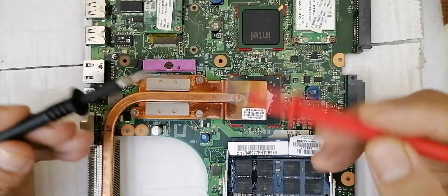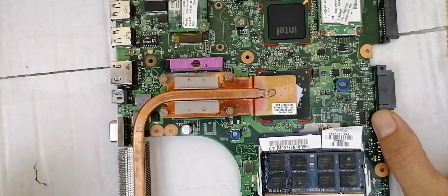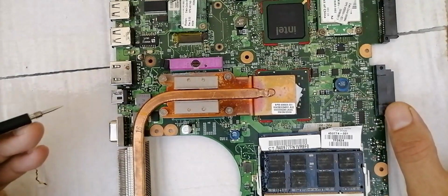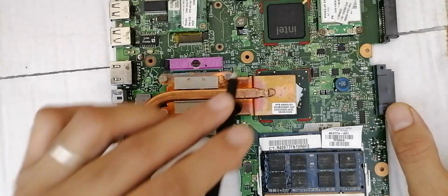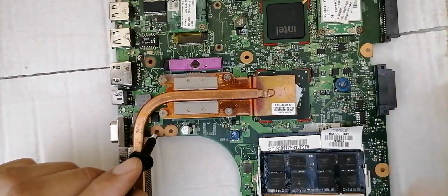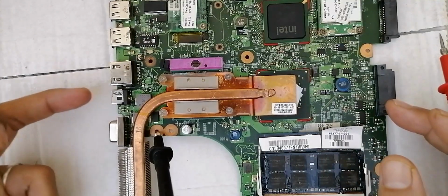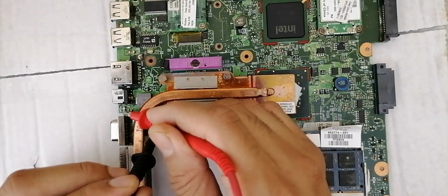Then what is the next step? In the fourth step, we are going to use the multimeter. We are going to use the multimeter and look for the main voltage. So for example, you can pick the ground everywhere here in the motherboard and put the black probe in the motherboard, and you can just connect the adapter here and check for the 19 volt in the fuse.